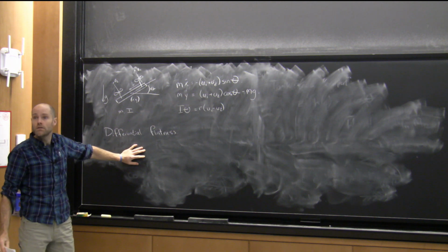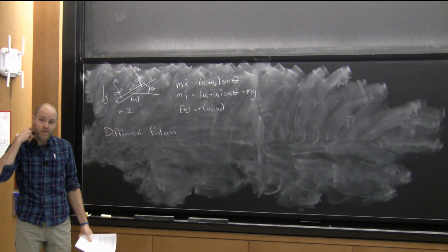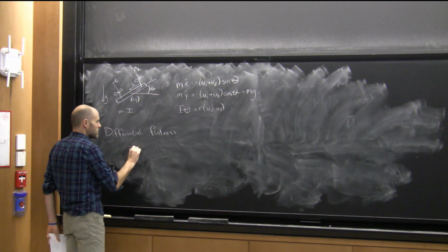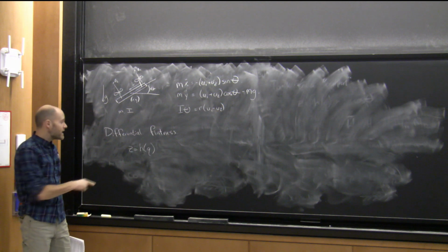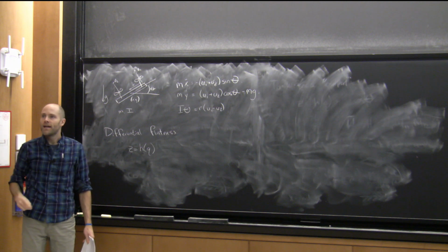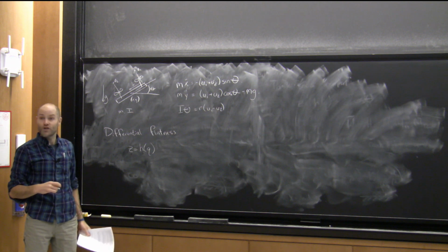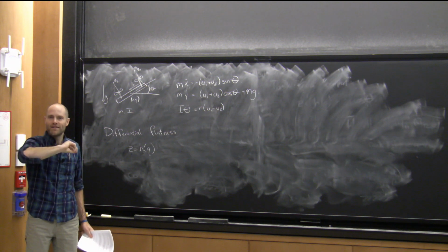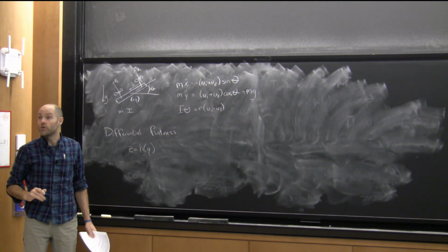The basic idea is that because my system is so constrained, it has fewer actuators than degrees of freedom. If you pick a few variables, pick my z equals h(q) again, let's say, and I give you a trajectory in z that you'd like to follow, if you've chosen z well, and the properties of differential flatness tell you how to check that, then in order to follow that trajectory in z, it tells me exactly what every other thing in my system has to be doing.